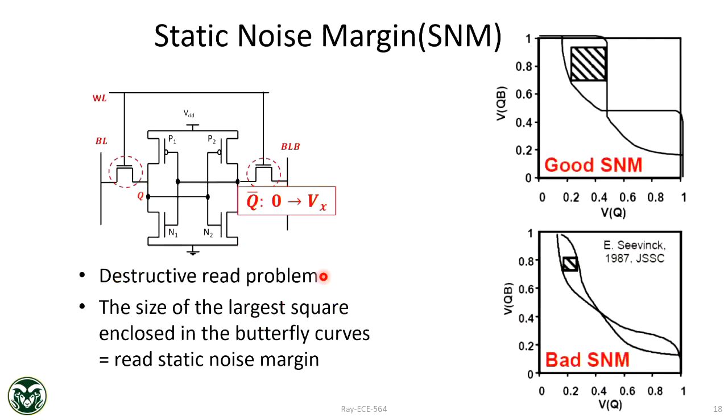Okay, so now techniques to improve noise margin. One is, of course, you can design SRAMs with high VT transistors. With high VT transistors, you can improve this noise margin curve. If you look at the diagram, this is definitely a better noise margin because you can fit in a bigger square. You can fit in a very small square, that means here noise margin is less. So that means it can flip, right? One of the transistors can flip and then you can go to a low state.